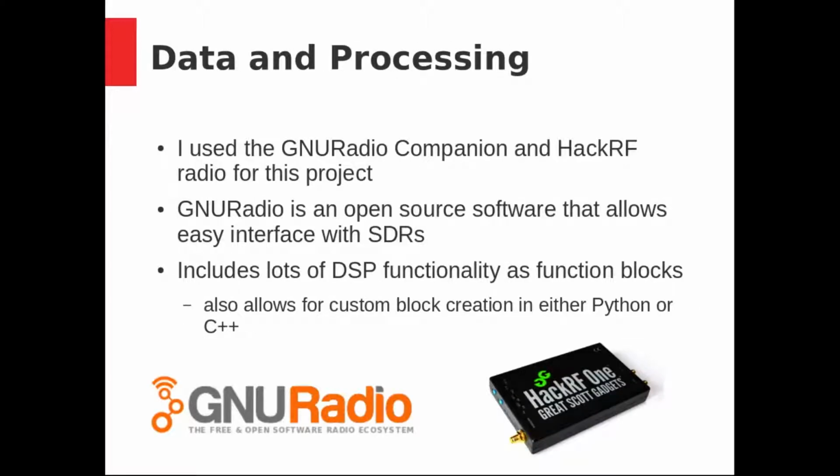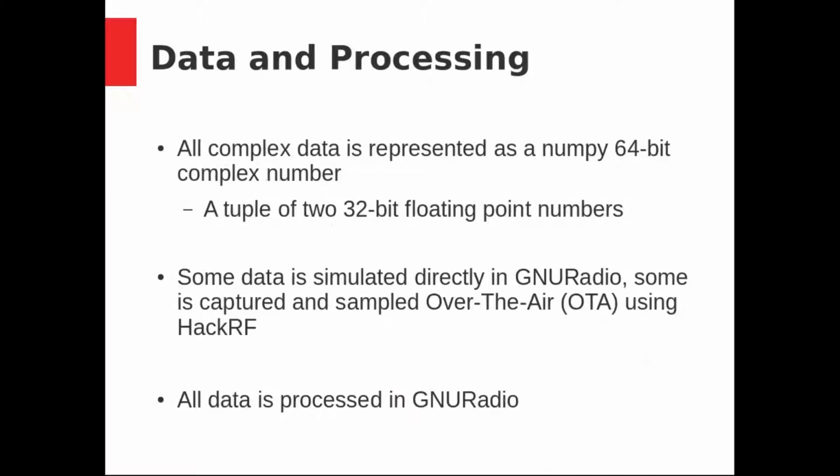I use GNU Radio Companion and a HackRF radio for this project. GNU Radio is open source software that allows easy interface with software-defined radios and includes lots of pre-made DSP functionality as function blocks, and also allows for custom function creation in either Python or C++, and I use Python for all my work. All the data in this is represented as NumPy 64-bit complex numbers. Some of the data is simulated in GNU Radio and others captured over the air and sampled with the HackRF, and I'll specify when each is happening.